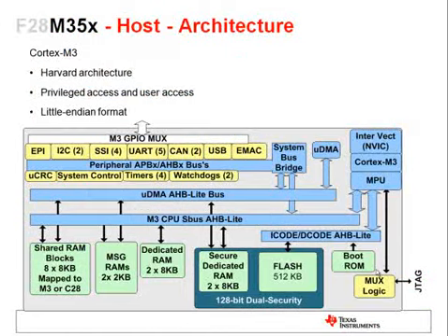Let's take a deeper dive into Concerto's components. As we mentioned previously, Concerto's host subsystem is based on the Cortex-M3 core, which is a 32-bit machine. It features a Harvard architecture characterized by separate buses for instruction and data. The beauty of this system is that it is entirely C programmable, even for boot code and system configuration. Some of the best features of the Cortex-M3 processor include integrated hardware support for interrupts through its nested interrupt controller, NVIC, to deliver industry-leading interrupt performance, and the memory protection unit for system reliability and to catch prohibited memory location accesses.